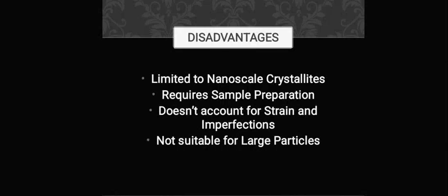Disadvantages. It is limited only to nanoscale crystallites, and it is most accurate for estimating the size of very small crystallites, and its accuracy decreases with increasing size. It requires sample preparation. Samples need to be prepared for XRD analysis, which can be time consuming and require specialized equipment. Doesn't account for strain and imperfections.